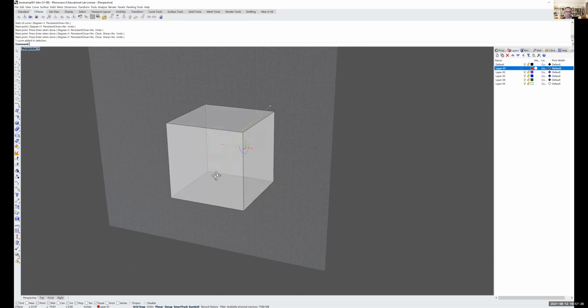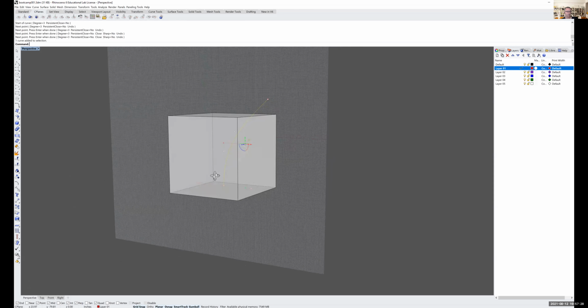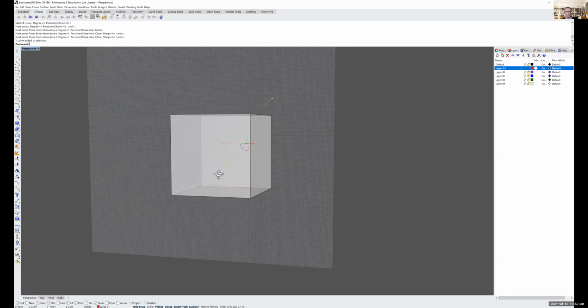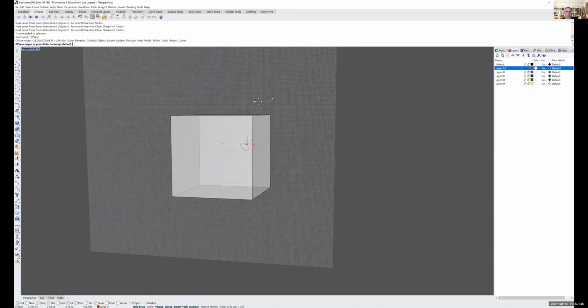So you guys have a curve in elevation you can work off of. So let's use this other tool, which is the fourth C-plane tool. Wait, 1, 2, 3, 4, the fifth one over, which is to set a C-plane perpendicular to a curve. And so what this allows us to do is to set a C-plane. You can see as I drag along that curve, it'll set it on there.